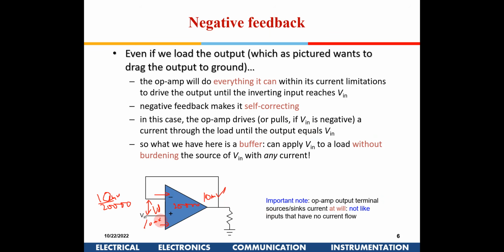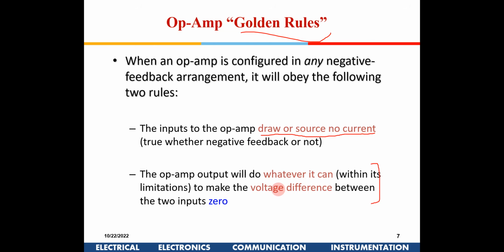For a high gain and a finite output, they will be close to each other. For an infinite gain, for an ideal op-amp, the difference divided by the gain will be 0. So for any negative feedback, these two terminals will follow each other. If you apply these two rules, then you will be able to analyze any kind of circuit and how it works.